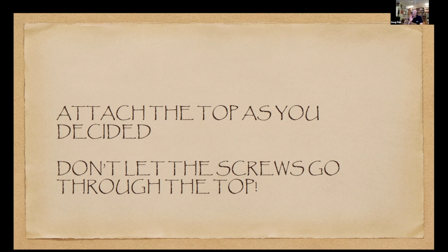I have a question. It has to do with your finish. You start with a heavily diluted amount of poly, and then you move on slowly to less diluted. I'm just wondering what your thought process is for going through those different variations of the dilution. The first coat I dilute significantly, as you noticed, simply because it makes the finish dry quicker. I'm using it as a filler coat or a seal coat for the very first coat.